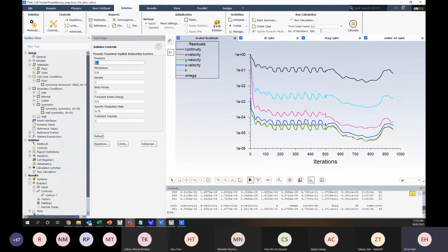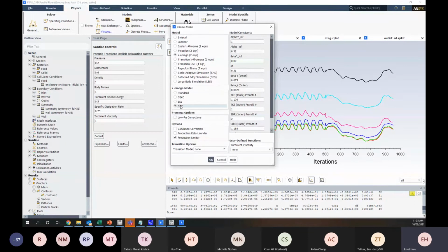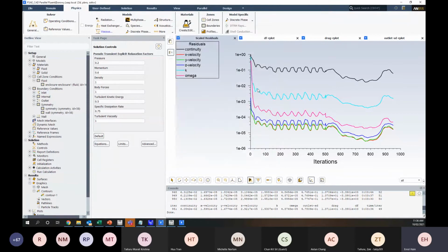How inaccurate would the calculation be if a finer mesh Y plus of 1 is used along with wall function? The wall function is an automatic specification. So when we turn on our k omega SST, it basically assesses what level of the boundary layer you've started in, and then uses either the wall function or a resolution of the viscous sublayer to suit. So you can't do both. In regions where the first layer height is around a Y plus of 30, it's going to use a wall model. In regions where you've actually resolved the Y plus of 1, it's going to use the full resolution.